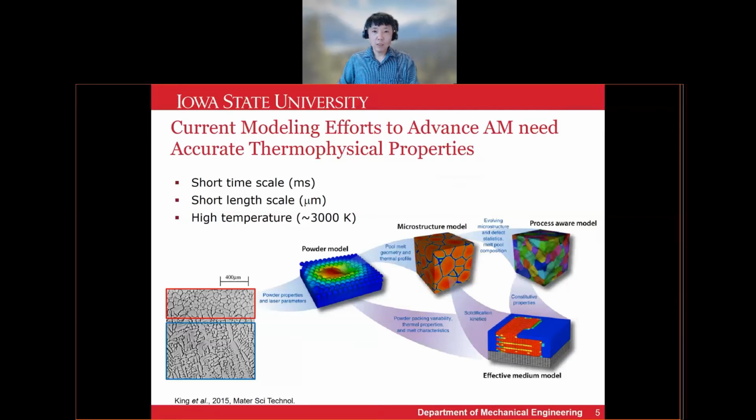One of the reasons why numerical approaches were adopted was that metal additive manufacturing processes are not easy to study solely by experiment because melting and solidification occur, of course, on a micrometer scale and a millisecond scale. For the case of in-space manufacturing, the role of numerical modeling could be even more important, as experimental studies are very limited. The result from the melting and solidification model will be input into the microstructure model.